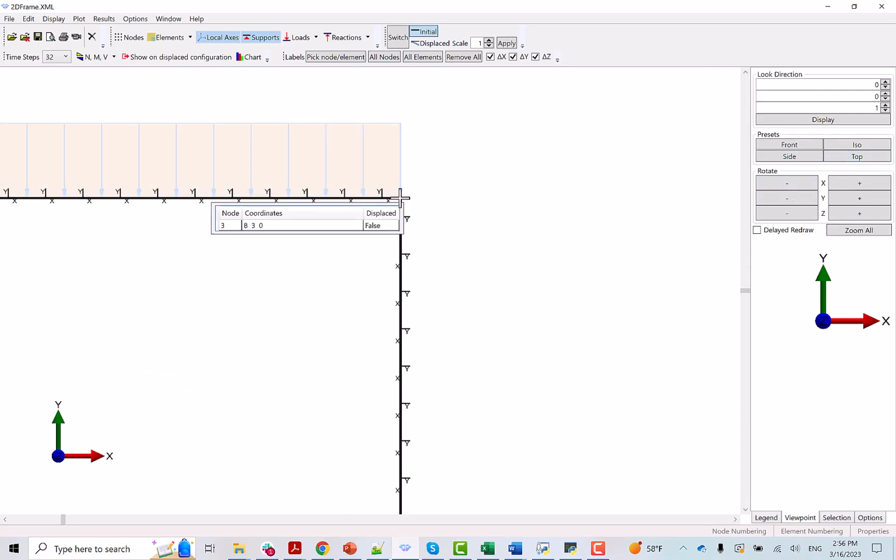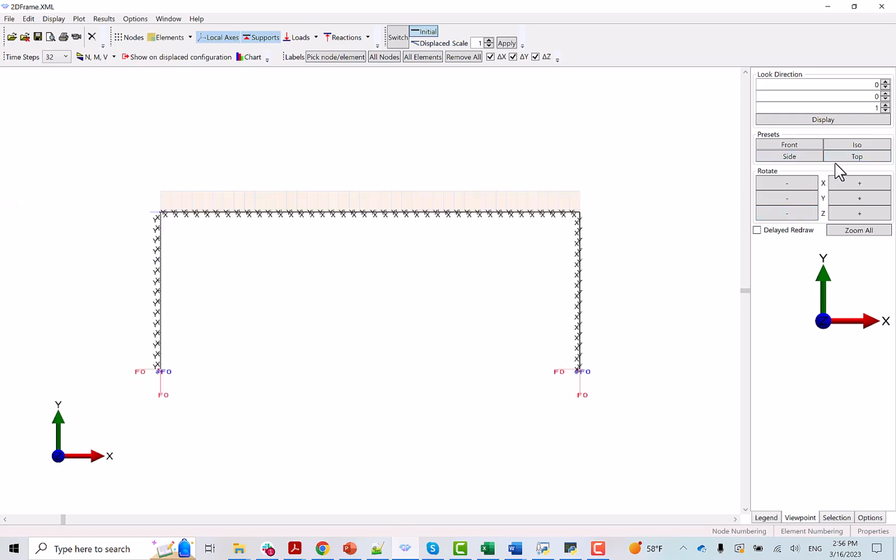This is why I defined for this column the X, or the starting point, being node 3 and the end point being node 4, in order to have X pointing downward and Y pointing outside of the compartment. This is because the positive Y is the face that is not exposed to fire in my thermal analysis.